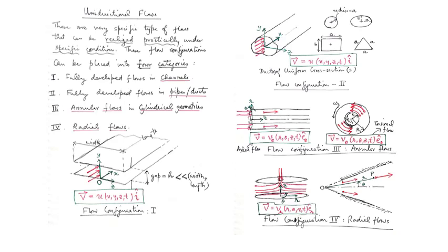And this last one, where we have rotating cylinders and the fluid in the annular region also undergoing a motion represented by concentric circular streamlines, because if the velocity field is as shown, then we will have concentric circular streamlines. So this flow is also known as a torsional flow. There can be other types of torsional flows also. This is the case of an annulus,